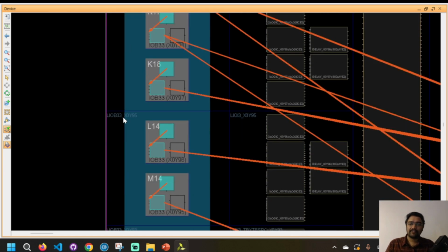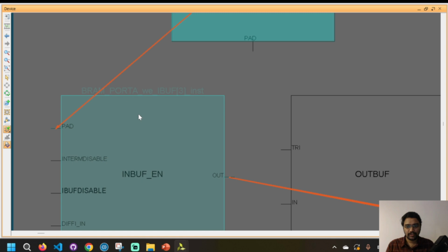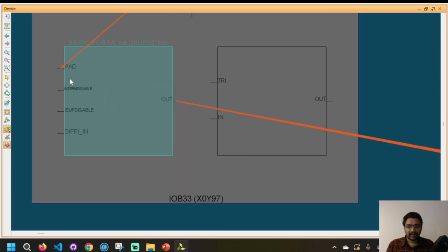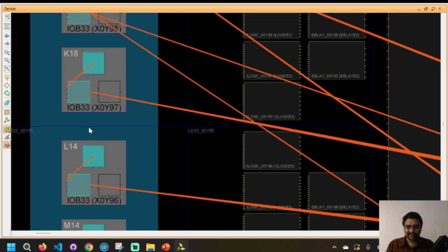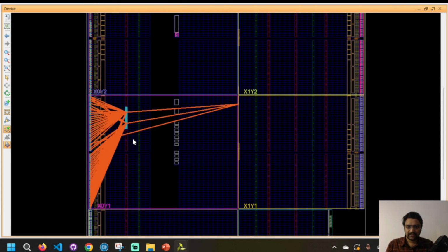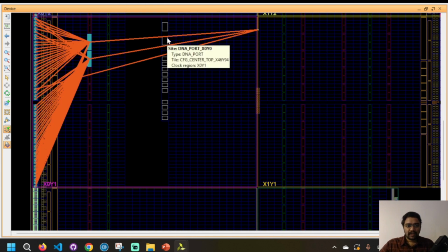So yesterday we connected one port called M16, which has an LED connection to it, an LED on the printed circuit board. Likewise, all these pads, and again, this is a pad. You can see BRAM pad, BRAM port A. We have assigned these ports for the BRAM. So each port will go through the input and output pads again. These pins will be sitting at the edge of the chip, and you can see the connectivity in this way. Got it, guys? So this is how you design.